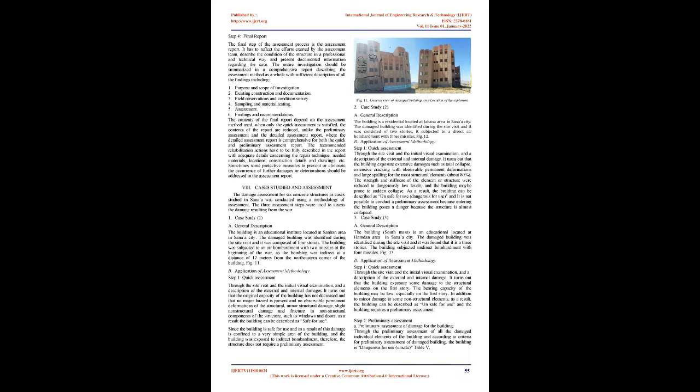Task 1, determine the force-resistant paths. Determine the force-resistant paths, explain why certain members sustained damage while other members were essentially undamaged, and know the safety of the building. Computer modeling is adopted by applying a complete simulation of the building after the occurrence of damage, and applying the loads on it during the occurrence of damage. This method gives a clear idea of the complete spatial behavior of all the elements of the structure, which helps to predict the locations of potential stresses that appear urgently as a result of the redistribution of loads in the elements based on the conditions of the new structure.